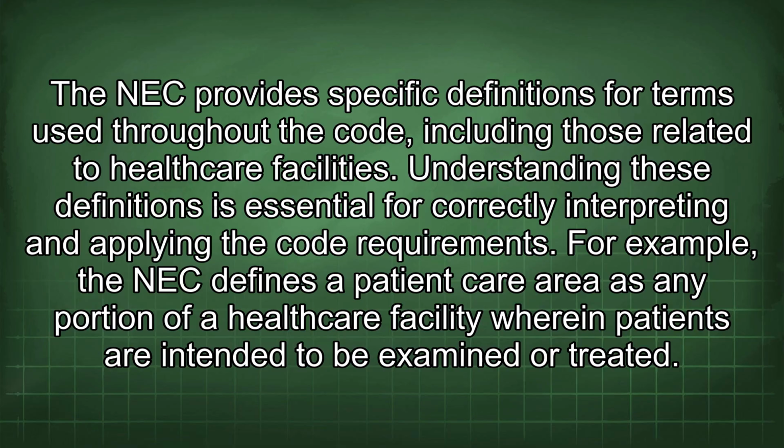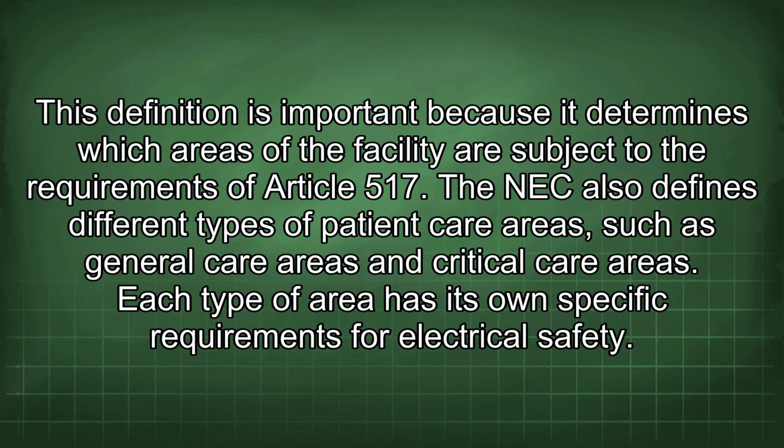For example, the NEC defines a patient care area as any portion of a healthcare facility wherein patients are intended to be examined or treated. This definition is important because it determines which areas of the facility are subject to the requirements of Article 517.